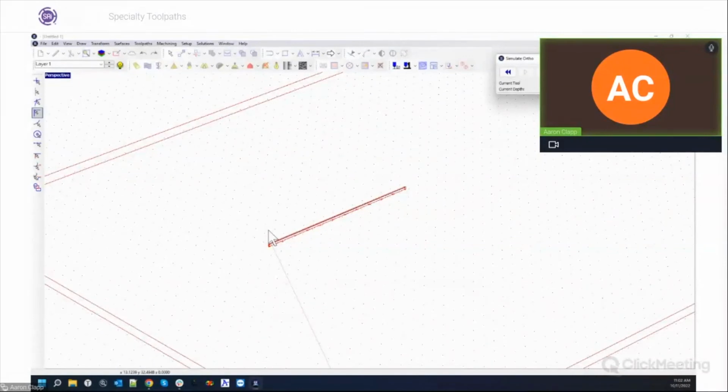That would be really useful to have a tool path that would retract it, go in and then come back out, because you're probably going to be cutting it from the side of the material, right? So you're going to come in from the side and then retract back out. Or perhaps you want to cut a slot along the side of a door or something like that. So you come in from the side, have it cut in, go all the way the length of the material, and maybe have it come back and pull back out in the same place.